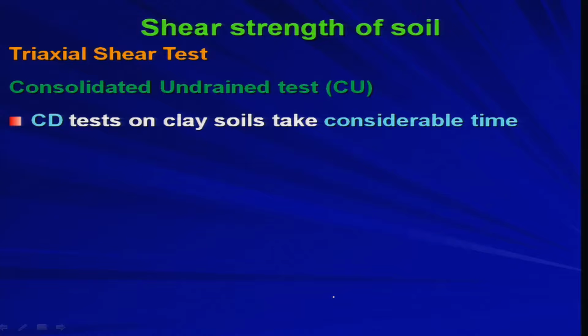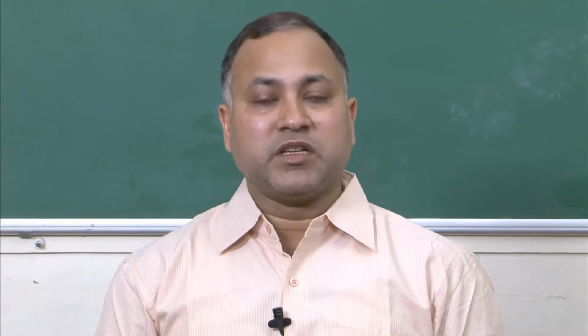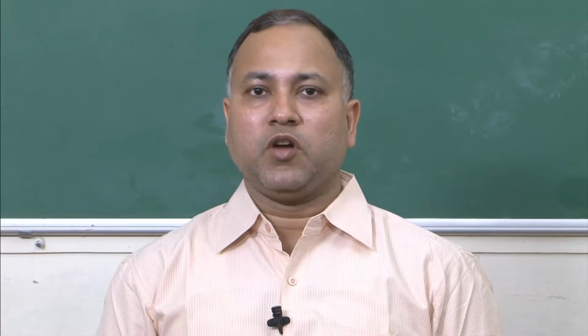So, CD tests on clay soil take considerable time, as we have already discussed. In case of clay soil, you know that permeability is very low, so the consolidation will take enormous time. If you perform a CD test, that means consolidated drained test, you have to allow the drainage and the complete consolidation. So, it will take considerable time, right. Therefore, the CD test is not very popular, not very common in practice.